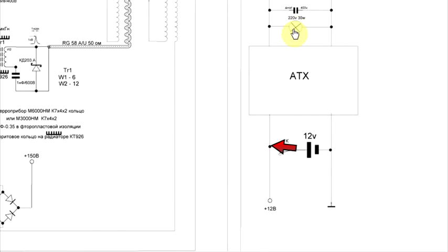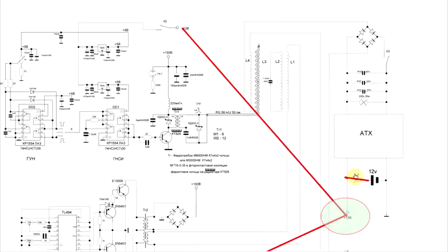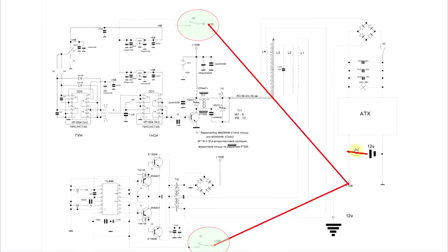After closing the switch next to the battery, 12 volts from the plus of the battery is connected to another 12 volt near terminal of switch K1. Also, the voltage from the plus of the battery is going to be delivered to the K2 terminal of the pulse forming circuitry, the upper one. Those arrows symbolize connections that have to be physically made in those points.